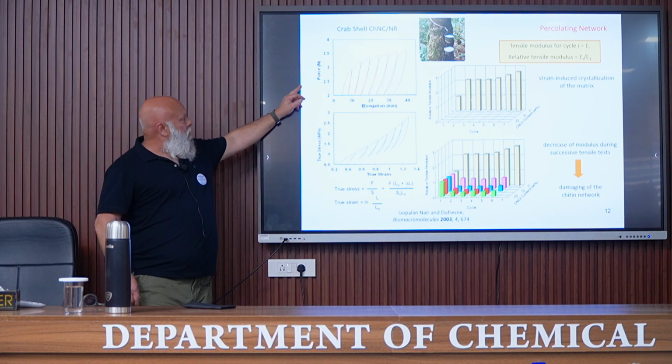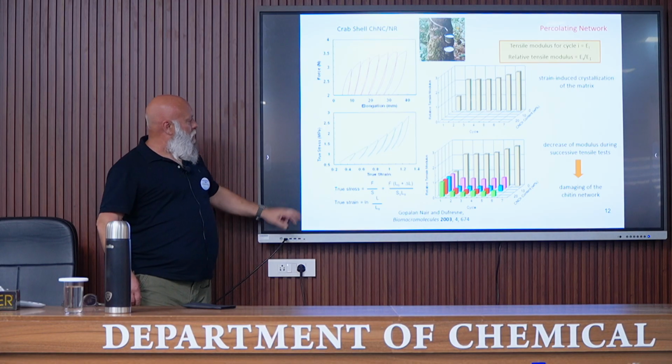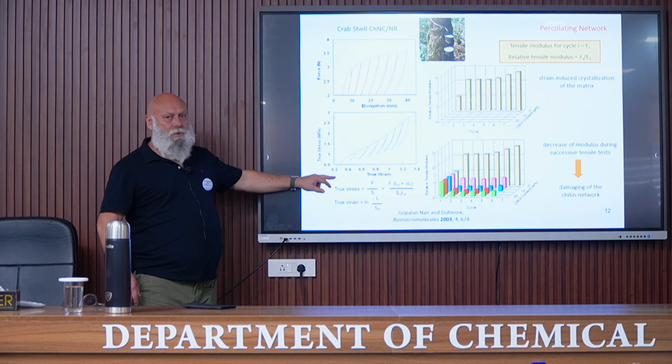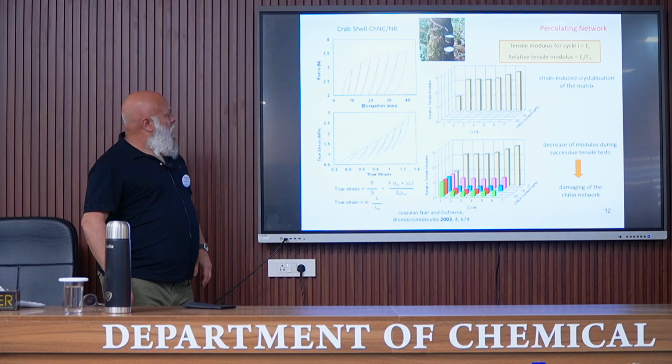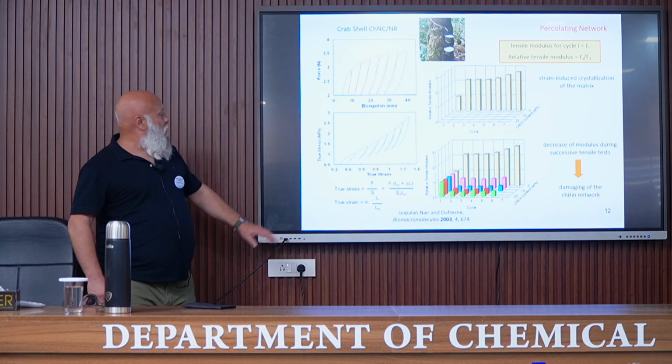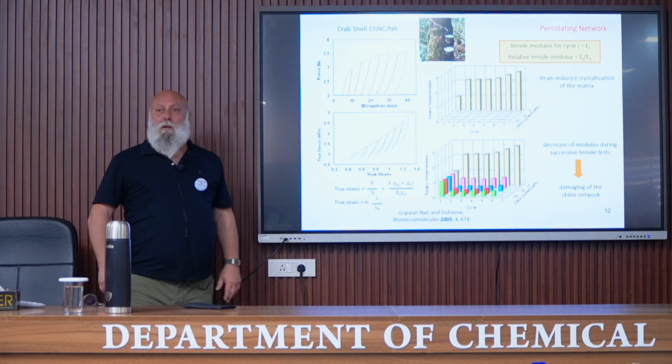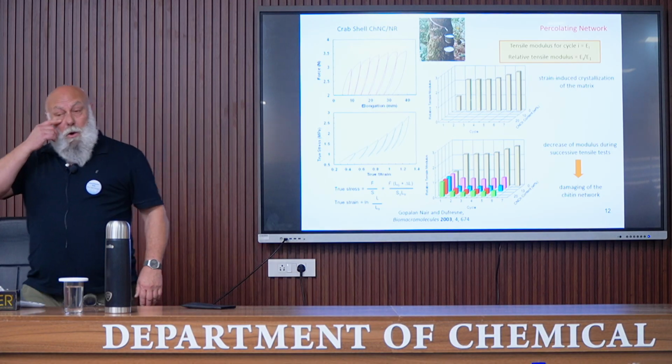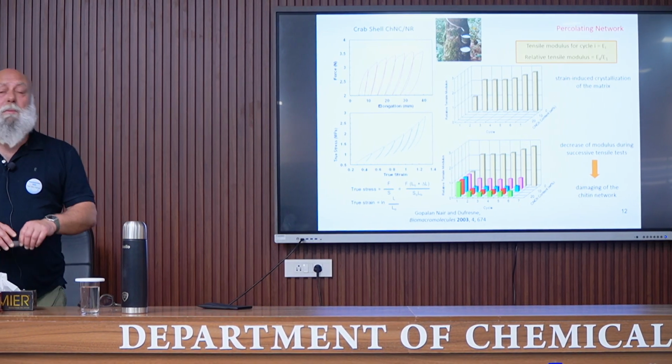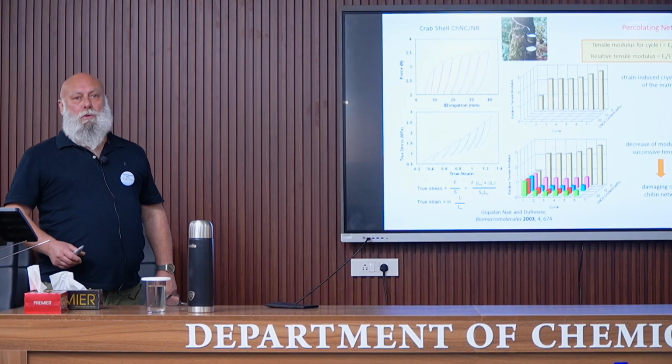We can convert this force-elongation curve into stress-strain, and of course, for each cycle, from the initial slope, it is possible to determine the modulus.